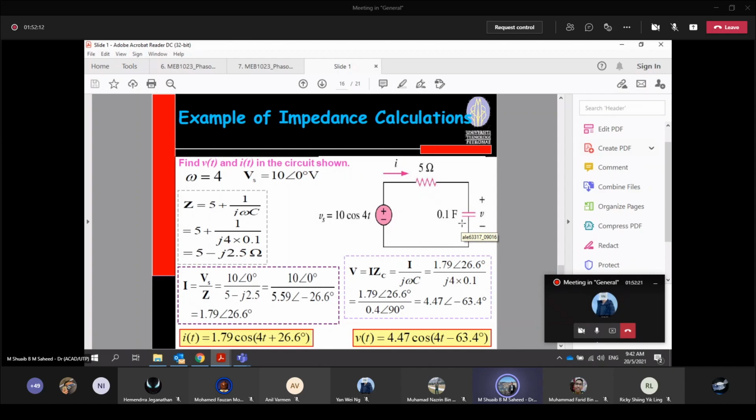So now, if I ask you to find the power loss or power absorbed by the capacitor, what should the answer be? 0, because the phase difference is 90 degrees, so cos 90 is 0. Cos theta here is the power factor, which we will cover in detail, but I would like you to be aware of that. The power loss is only at the resistors.